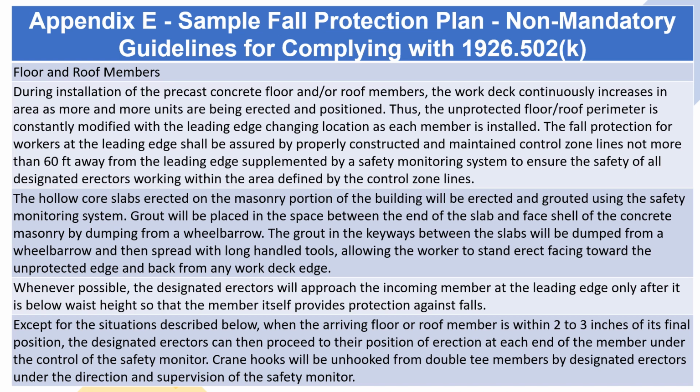During installation of the precast concrete floor and/or roof members, the work deck continuously increases in area as more and more units are being erected and positioned. Thus, the unprotected floor/roof perimeter is constantly modified with the leading edge changing location as each member is installed. The fall protection for workers at the leading edge shall be assured by properly constructed and maintained control zone lines not more than 60 feet away from the leading edge, supplemented by a safety monitoring system to ensure the safety of all designated erectors working within the area defined by the control zone lines.